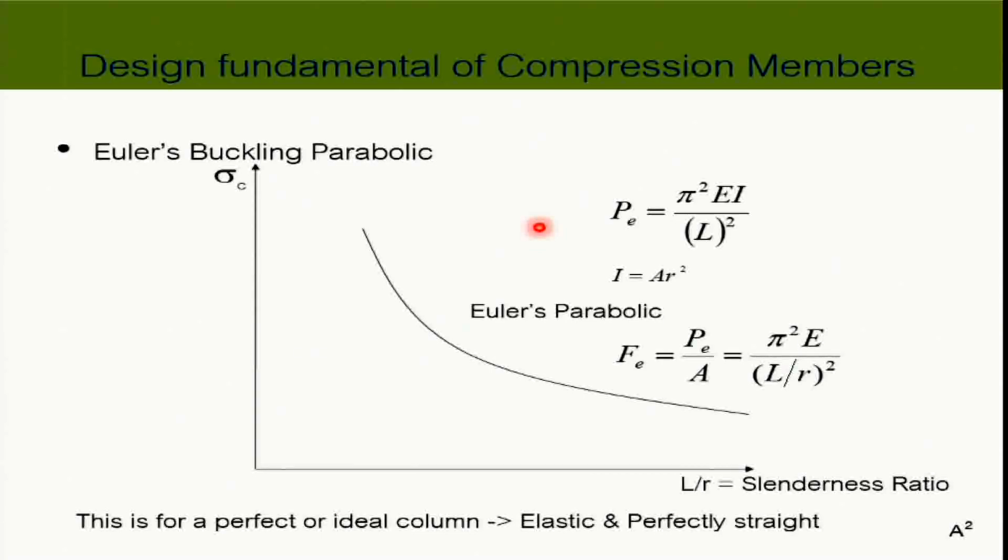This is theory, and it is correct. And it says that here, see, it's a stress, but this is not yet Fcr. It's not yet a critical buckling stress. This is the elastic buckling stress. At first, I thought the e in Fe stood for Euler, but no, the e is for elastic buckling stress. It's a theoretical buckling stress, which means that it's a theory. We cannot use it as is. We need to incorporate some application into it so that we can use this discovery to approximate the strength of the column.